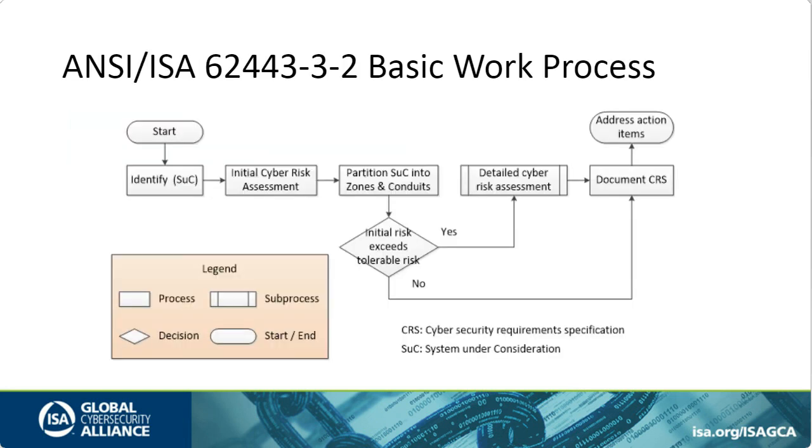Now let's get into the basic work process that's documented within the standard. This is the overall view of the entire work process. You'll notice that the detailed cyber risk assessment is in a sub-process box. So later on, we will expand that particular aspect of the work process into an expanded flowchart. So the first thing is to identify the system under consideration. That's going to be the scope of your hazard review.